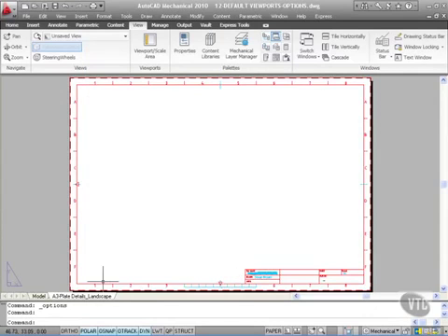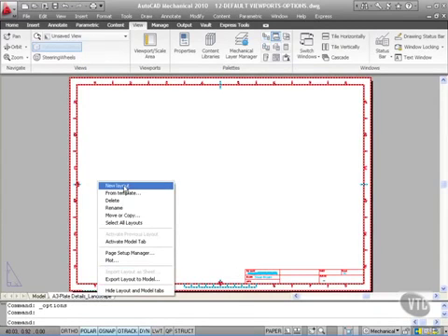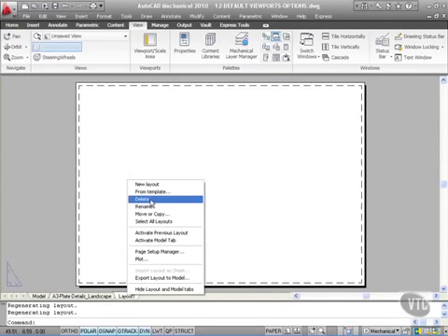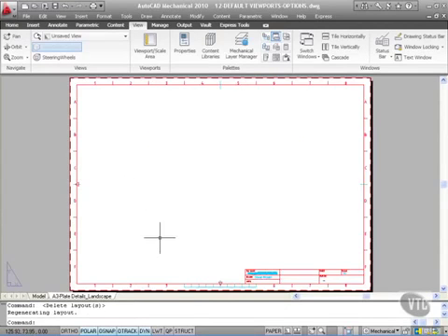Let's just check that quickly. So it's a right click, new layout, there's Layout 1 there, no viewport, so I can now right click and delete Layout 1, and then I'm back to my A3 plate details landscape tab with my title border ready to go. So that's how you set up those default viewports and switch them on and off using your options dialog box.